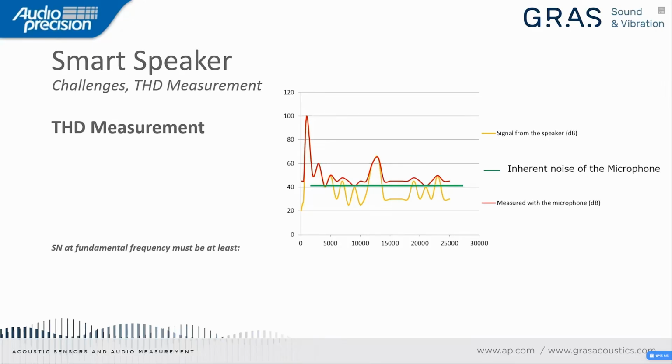Normally, when we are doing rub and buzz, we would like to see between the 14th and the 20th harmonics of the fundamental frequency.